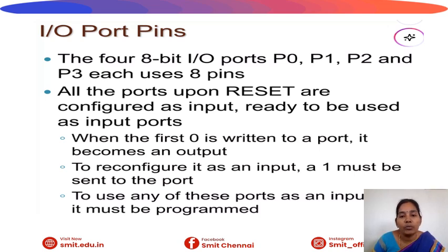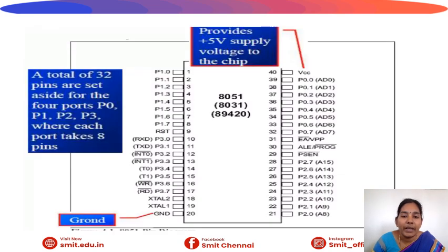We can use the ports first. You have to reset as configuration in input port. When 0 is given to the port, it acts as an output port. To configure it as an input port, you must put 1 on the port. This is the pin diagram of the ports. There are 4 ports: port 0, port 1, port 2, port 3 and external pins.